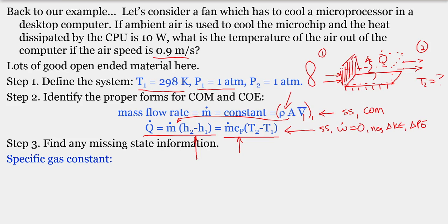So first of all, this dimension is going to be whatever the characteristic dimension of the CPU is. Depending on whether it's a square configuration or a rectangle, we're probably talking about something on the order of a centimeter or 2 in this dimension. Now, in terms of the dimension above the surface of the CPU, the heat transfer occurs entirely within what's referred to as the thermal boundary layer. So we would need some estimate of what that distance is for the thermal boundary layer.